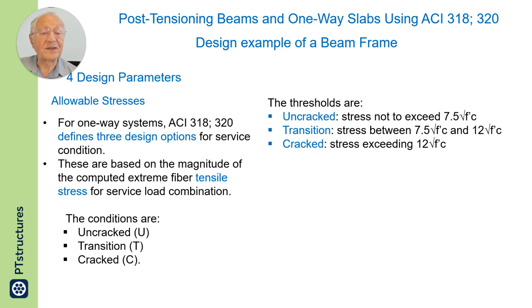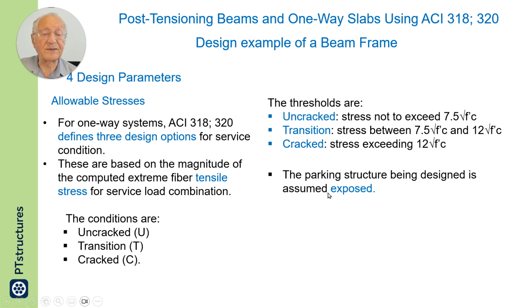This definition determines the serviceability check. But when it comes to the safety check, all the 3 stages are handled the same for determination of the rebar, if necessary, for the safety condition. But for service condition, that means deflection, we will have to follow this classification.